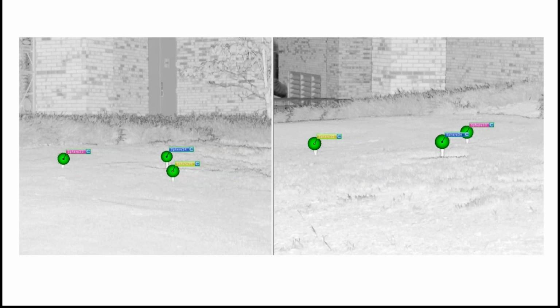In this screenshot, you can see this was a scan or several scans taken outdoors, and we were using a targeting method to register these scans together. The software understands the relationship between all of these spheres, and so it's able to intelligently tell one from the other and then give them common names from scan to scan. The spheres are automatically detected, so the software understands how to go and look through the point cloud and find spheres.